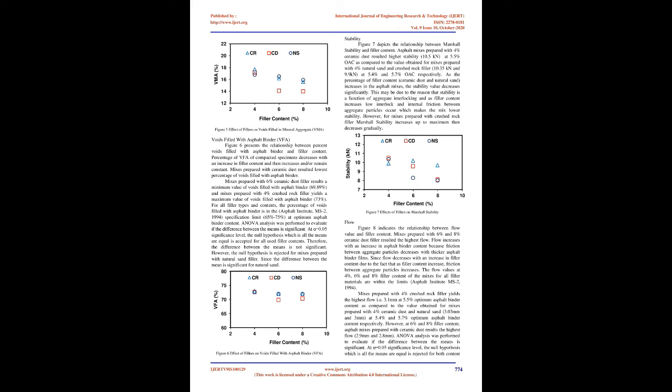ANOVA analysis was performed to evaluate if the difference between the means is significant. At α equals 0.05 significance level, the null hypothesis, which is all the means are equal, is accepted for all used filler contents. Therefore, the difference between the means is not significant. However, the null hypothesis is rejected for mixes prepared with natural sand filler, since the difference between the means is significant for natural sand.